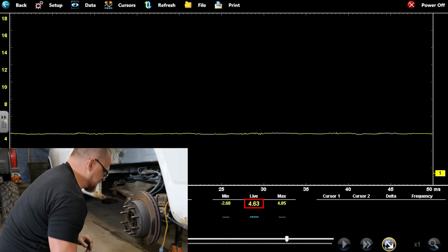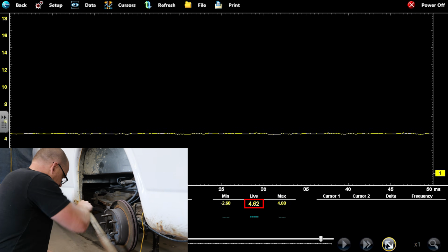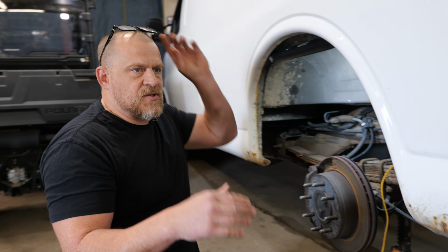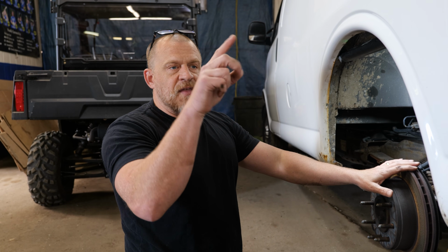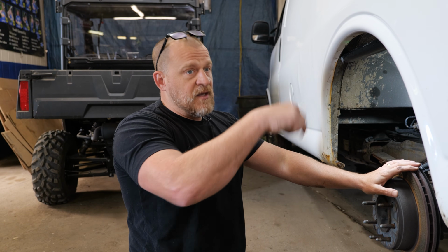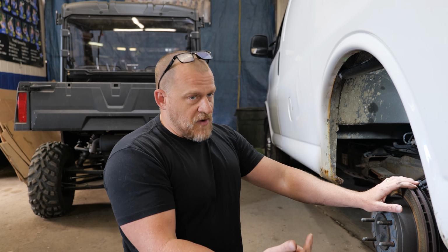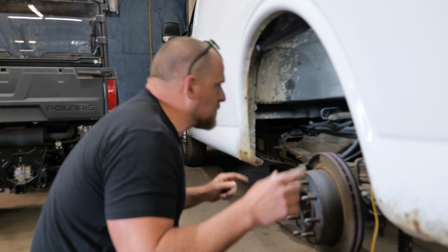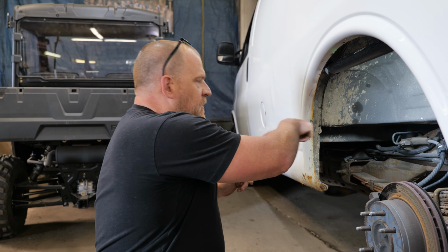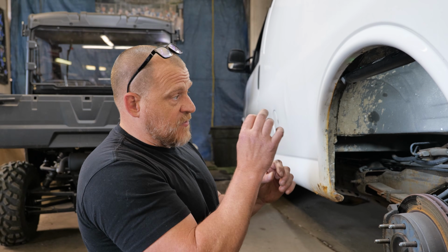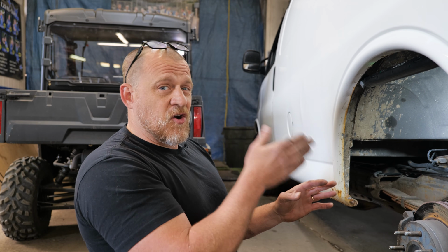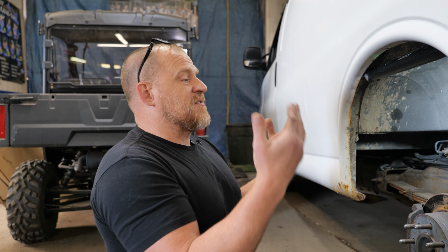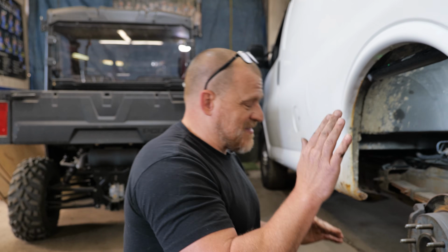This is showing me 4.6. And is this the one the square wave rides on? Let's see. On some of these digital sensors, they'll send a 12 volt feed and then they'll ride the square wave on the feed. And on others, it'll ride on the ground circuit. Okay, but I think that voltage is low, which is why it's flagging this. So that means we're probably gonna have corrosion in the wire. We're gonna have a break or a chip in the wire somewhere, and we have a voltage drop that's occurring. It's enough voltage for the computer to see the signal, but it's flagging the code because it's not the right level. That's what I think we're looking at.